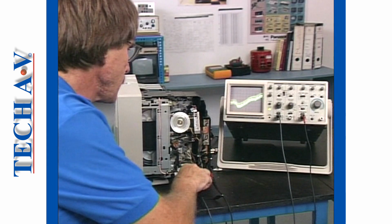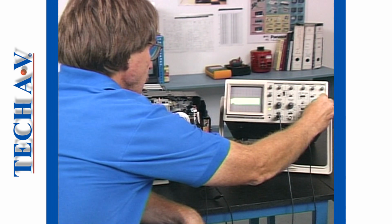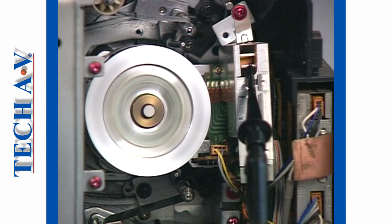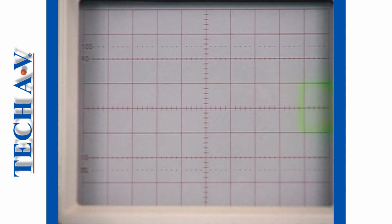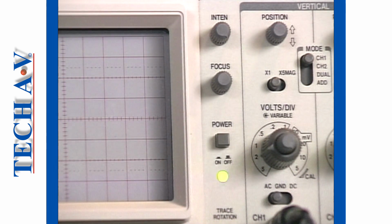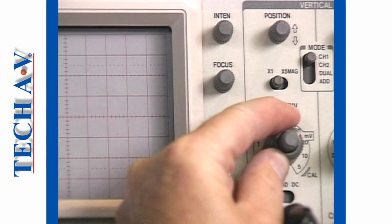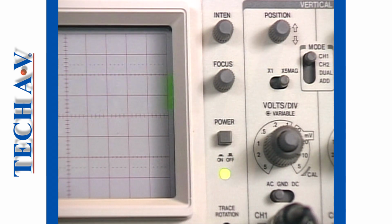For example, when examining the head output signal of a video cassette recorder, the trigger must be externally derived from the head switching pulse circuit, since the head signal itself is unable to provide a reliable trigger signal for the horizontal time base. When viewing very small amplitude signals, it is a good idea to make use of the ×5 magnification facility to amplify the signal. The actual amplitude of the signal is then 5 times the value indicated on the volts per division switch.